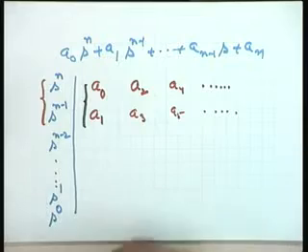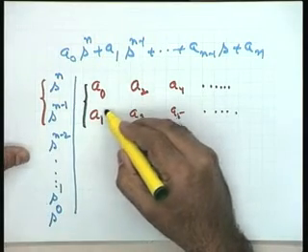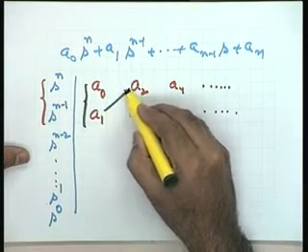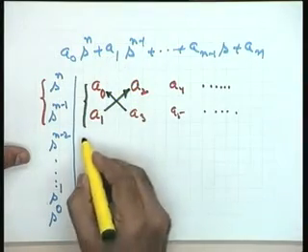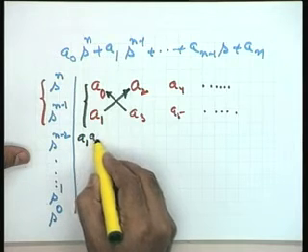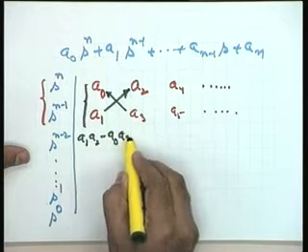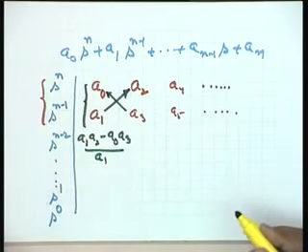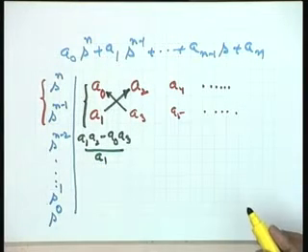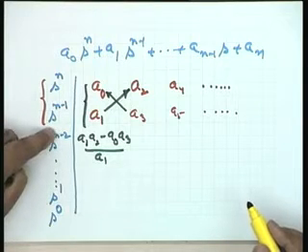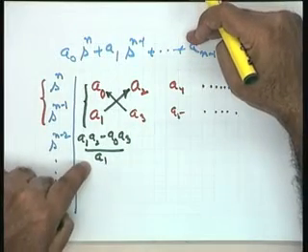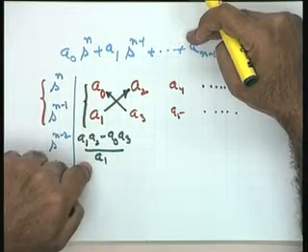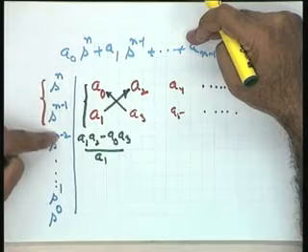I take this pair, take up this coefficient a1, multiply a1 with a2, a naught with a3 and write the coefficient here: a1 a2 minus a naught a3 divided by a1. This is the first coefficient of the row s to the power of n minus 2. Now, please note that s to the power of n minus 2 has lost that meaning. It should not confuse you. It is only an index of the number of rows.